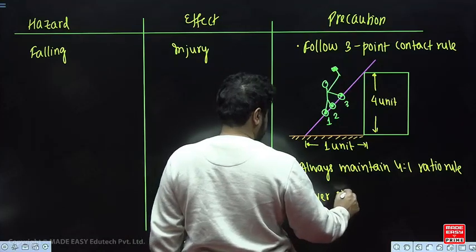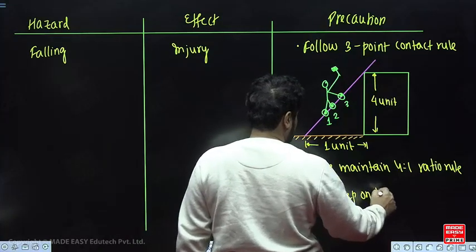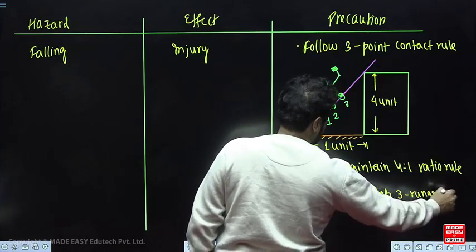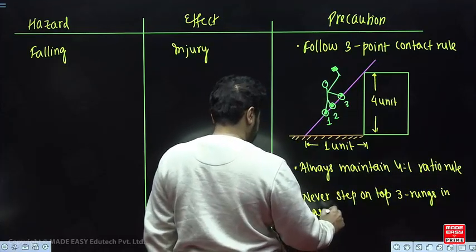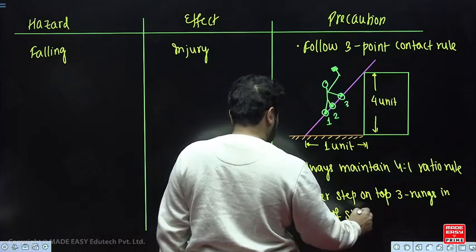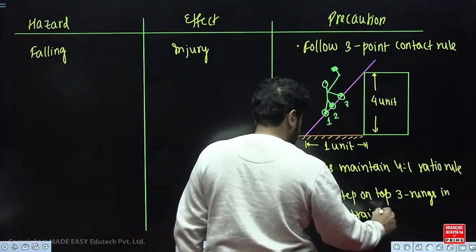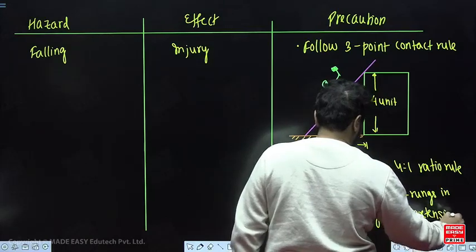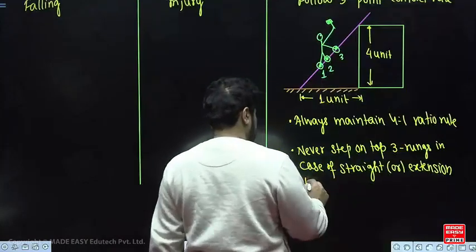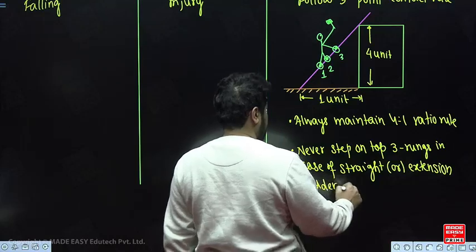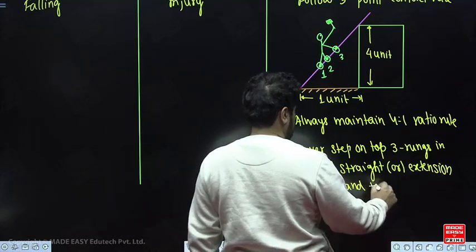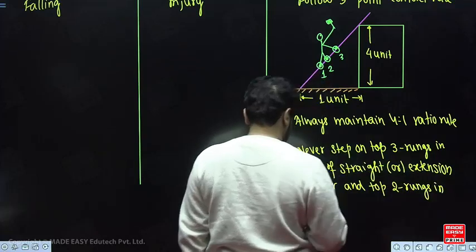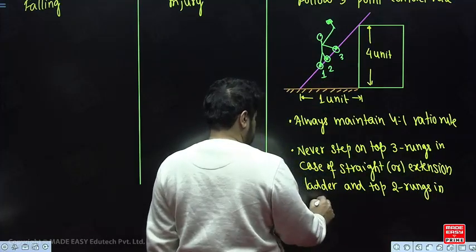Never step on the top 3 rungs in case of a straight or extension ladder, and the top two rungs in a step ladder.